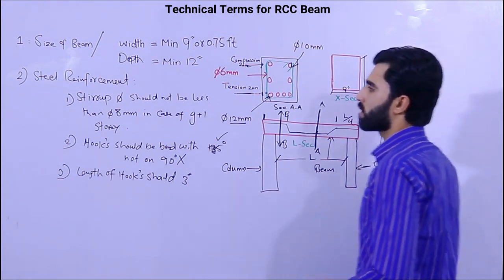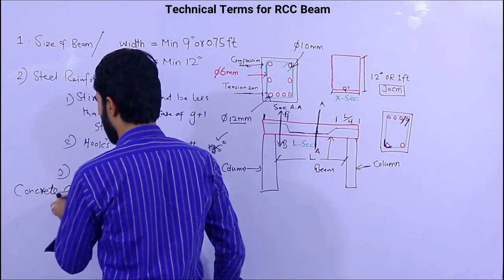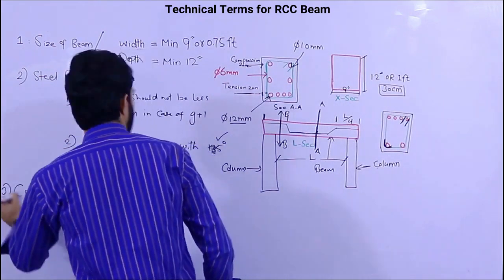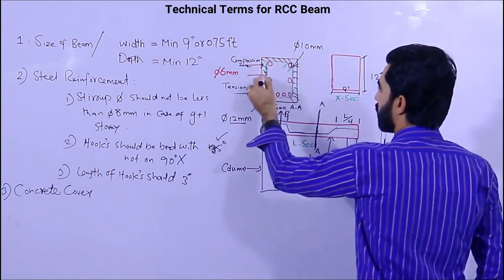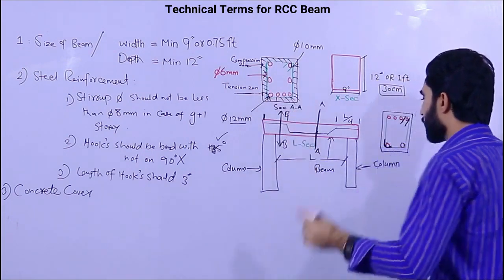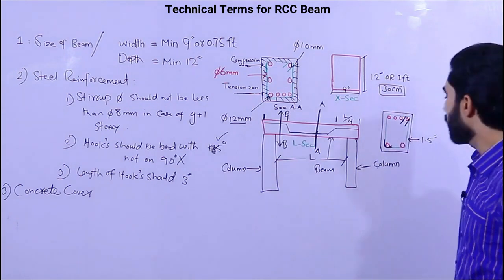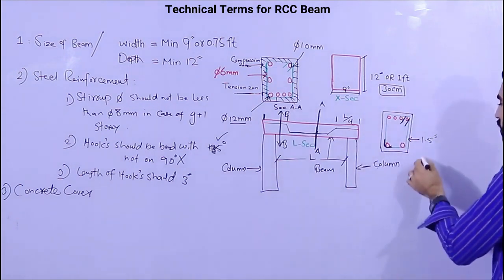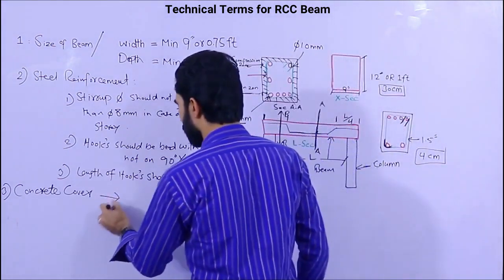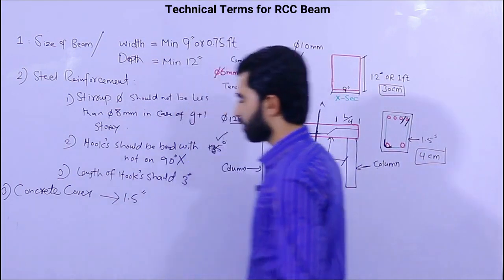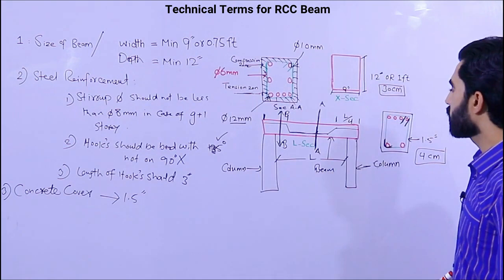Now guys, when you come to concrete cover, the third number is concrete cover. This concrete cover should not be less than 1.5 inches, or you can keep about 4 centimeters. So concrete cover should be 1.5 inches, right? This is also concrete cover for this.